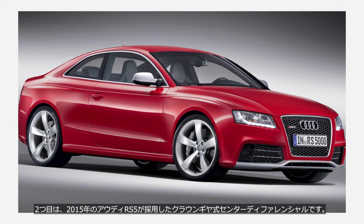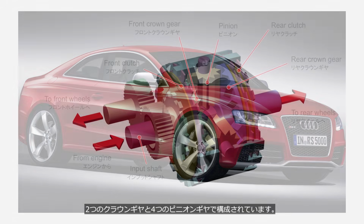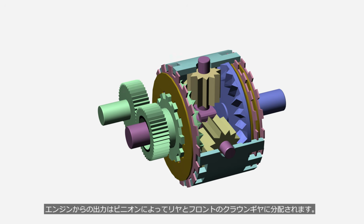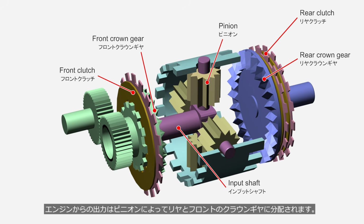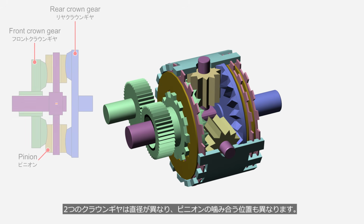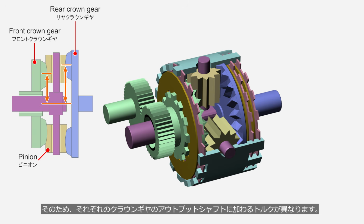The second example is the crown gear center differential, adopted by Audi for the 2015 RS5. It consists of 2 crown gears and 4 pinion gears. Engine output is distributed to the rear crown gear and the front crown gear by pinion gears. Those 2 crown gears have different diameters, and the pinions mesh with them at different positions. As a result, different amounts of torque are applied to the output shafts of the 2 crown gears.